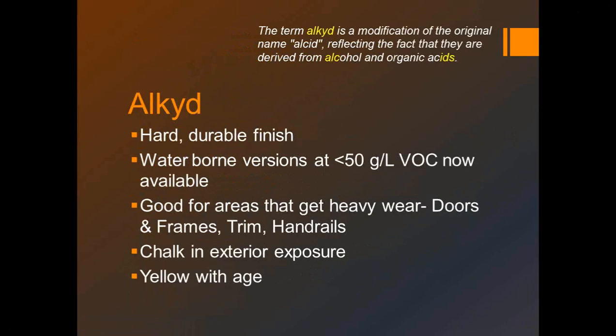The paint primer in one type situation tends to be some marketing aspect of it to a certain degree, because you've been able to take 3 coats of latex paint, put them on bare drywall, and get a relatively decent finish forever. The only issue is that finish coats tend to be a little more expensive than prime coats. So if you use a primer and 2 finish coats, you may be able to save yourself a little bit of money in terms of material cost by doing that, if you don't mind changing out your roller cover or cleaning up your roller cover and switching to finish coat from prime coat. But if you like one bucket, all one size fits all, for drywall particularly, that's great.